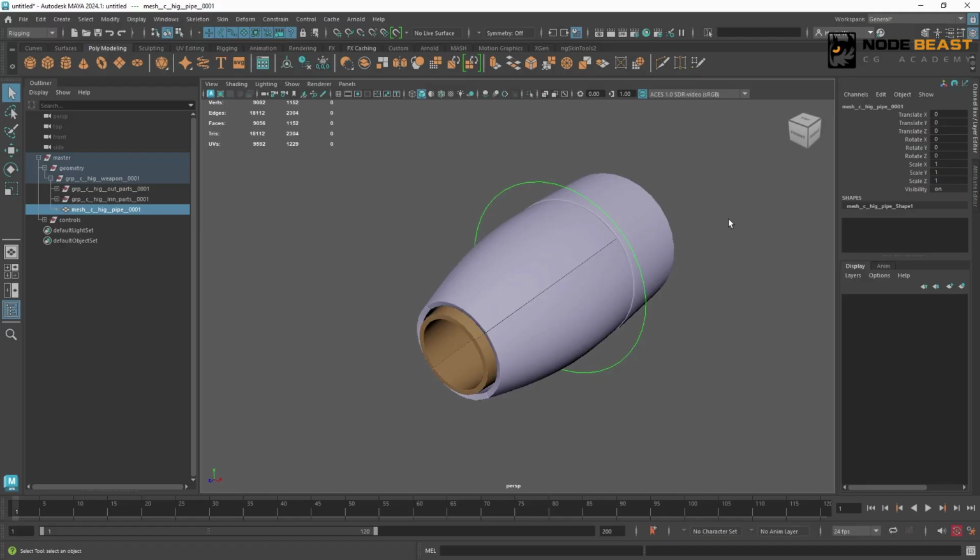First is the same reason as our previous exercise. When we set things up directly on the model, it's very difficult to make changes. Also, our scene will have a lot of extra unnecessary nodes, which will slow down our rig. Another reason is because when we're creating these transformation effects, a lot of the time, we need to define the pivot points ourselves. For example, when we rotate or scale, we might not be satisfied with just operating from the world origin. But our models, when they're created, all of their pivot points are at the world origin, so we don't operate on the model itself.